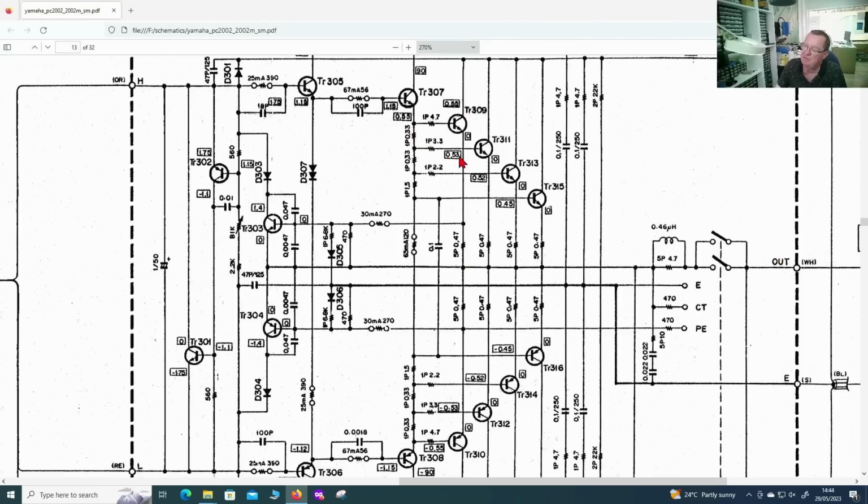0.2 volts higher, this one comes on. So we now have 2 transistors driving the speaker, and you can see just after that, 0.52, this one comes on, and then sometime later, quite a while later, another 0.7 volts on the drive, this one comes on. So effectively, as the AC waveform goes up, we're switching more and more transistors on.